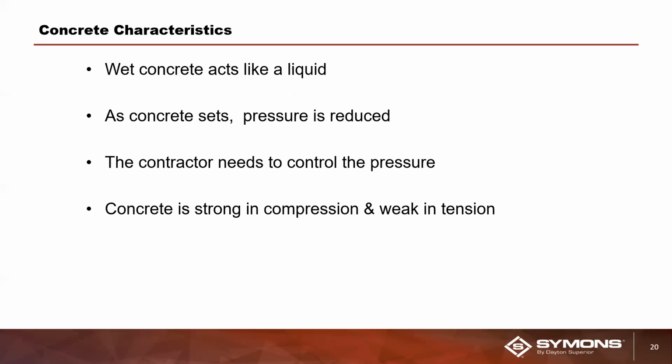Concrete characteristics. Wet concrete acts like a liquid. It's in a fluid state, so it will flow. As concrete sets, pressure is reduced. So obviously, as we showed you earlier in the slide, after an hour that bottom foot of concrete is null and void. And then for every foot, however long it took you to pour the next foot, once you get to that level, 1 hour after you started pouring that, it is cured and the pressure is then reduced.